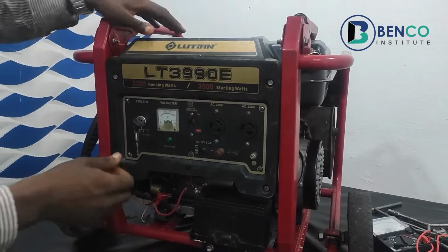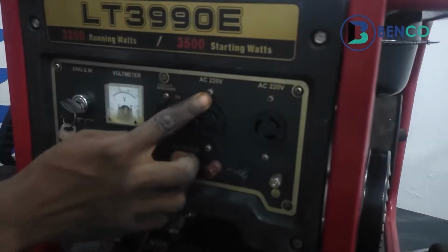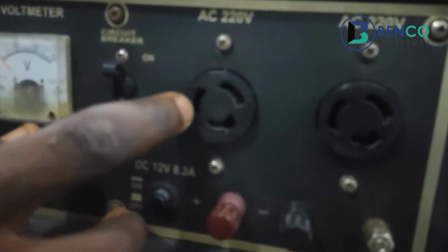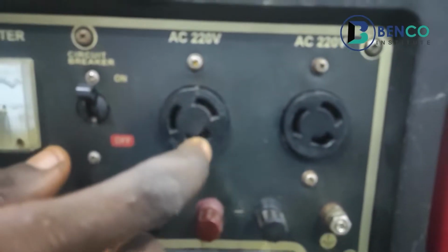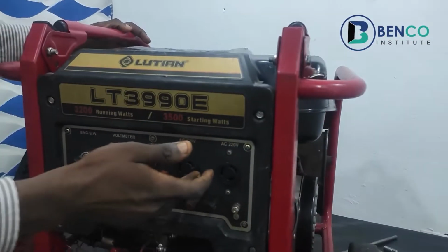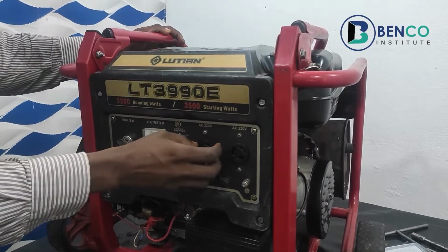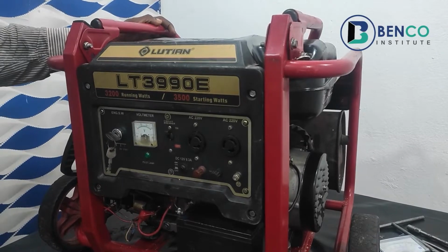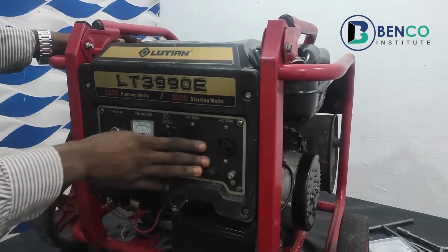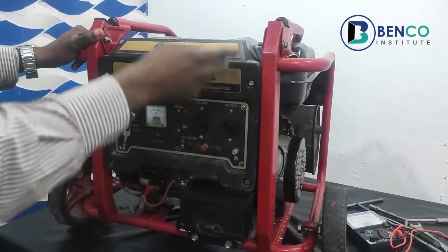The first thing to do is to look at these sockets. You look critically at these sockets. Look internally to see if there's burn anywhere. Is it heated up? If it's heated up, that means there's a possibility that the wire that connects down to this has been disconnected because of burn. It's very possible. But looking at this particularly, there is nothing like that. The socket is very much intact.